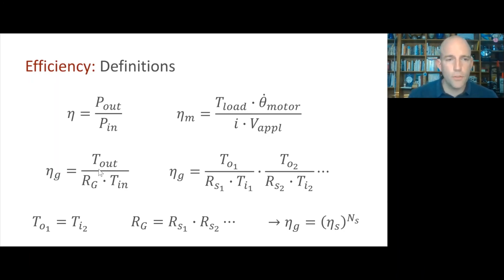And if we did this for a few different values of output torque, measuring I and calculating what the load torque is in each case, we get a few different estimates for the overall gear efficiency, and we could average them to get a robust estimate.